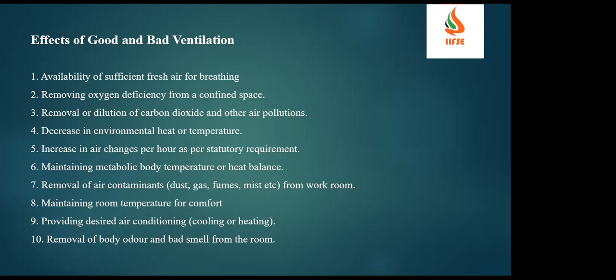Whenever you're in an area where the temperature is very high, slowly the air inside that specific room or work area also starts getting heated up. Whenever you provide good ventilation, the heated air, being lighter than fresh air, will always try to escape. Then the fresh air tends to come in, because whenever the hot air goes out, automatically a gap is generated, and then the fresh air comes in.